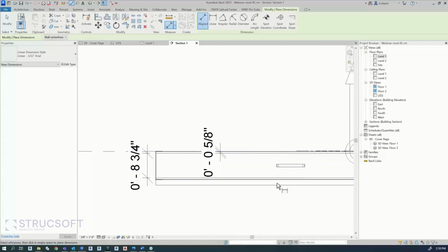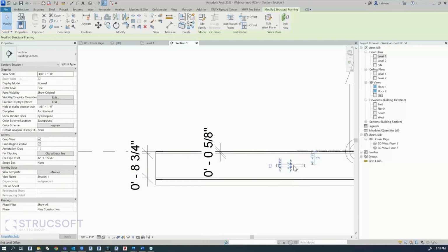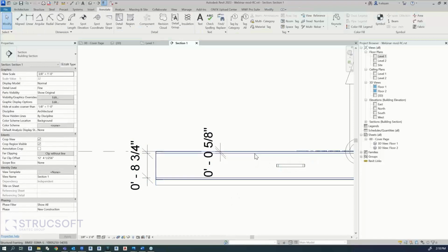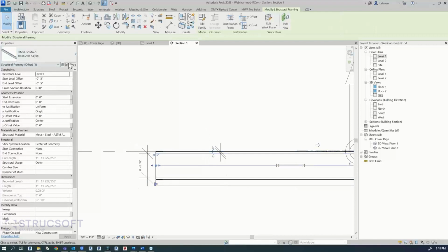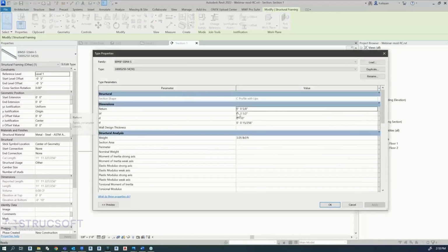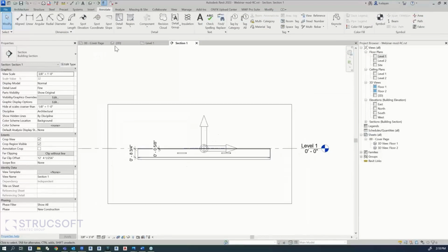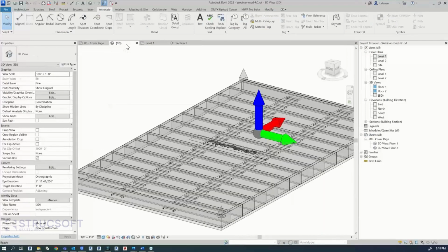So that's one thing. The other thing is because I want to know the size that I need to use for the squash block member. It needs to fit in here. So I'm probably going to use like a 6-inch member. And another way that you can find out this information is to actually select the family. If you click on edit type, and if you go here, it says the number of the return. This is the size of the return. That's another way. And that's it for now. That's all I needed to know.